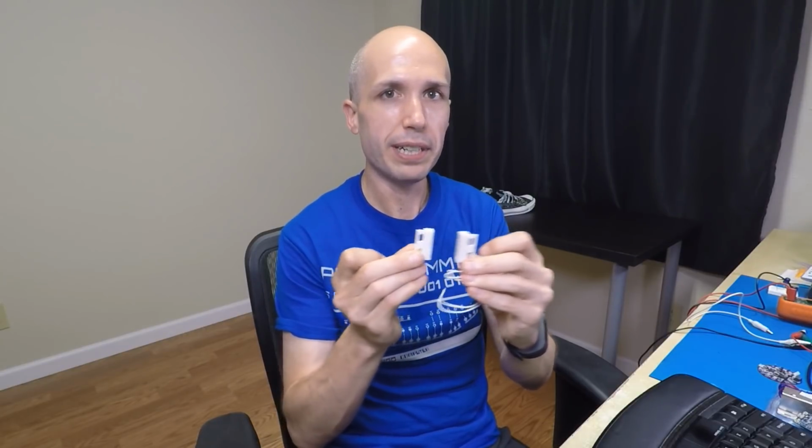And then we also saw how to use a digital input. So that's how to read a high or low logic level, like you might get from a toggle switch like this. You flip the switch into different positions and you're able to read that as a high or low logic level. Or we saw other types of switches, like this magnetic switch right here, where it can detect if a door is open or closed, for example, just by having these two connections connected together or not. So we saw how to read that with a digital input object.